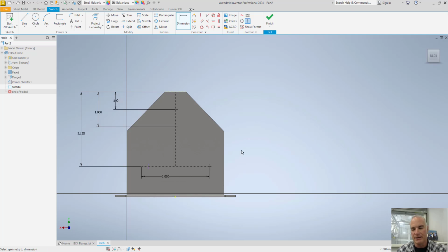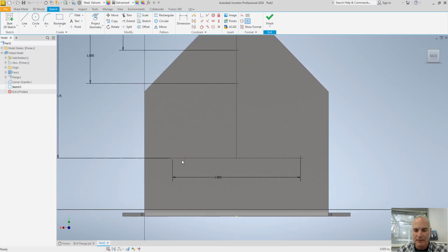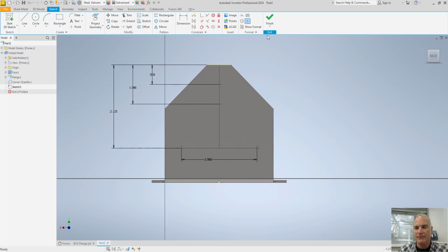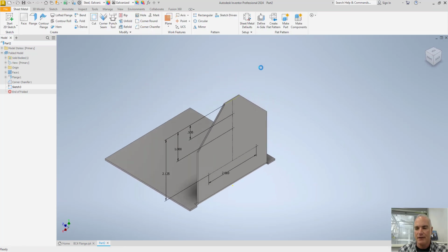So again, by doing this, notice that I've got everything ready to go here. This is telling me, oh, I missed that one right there. That should have a coincident constraint with the endpoint. I missed that one. So we are now fully constrained. So now I can save this, finish the sketch, and I can put my holes in. Now, again, this is going to be a larger hole than these other 3, but I'll go ahead and use the hole tool to do that.